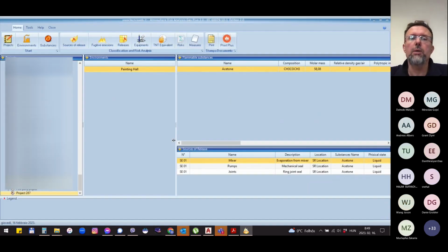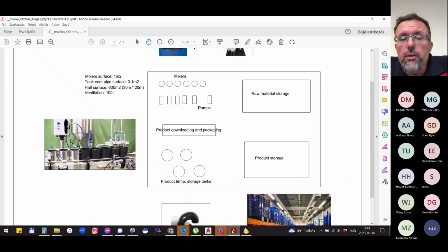And if you look at the type of zone, it is negligible extent, yeah. And no EPL has been defined, but certainly that shall be the decision of the engineering team, that even in negligible extent, you define an EPL, okay? So that's again the way of engineering decision.